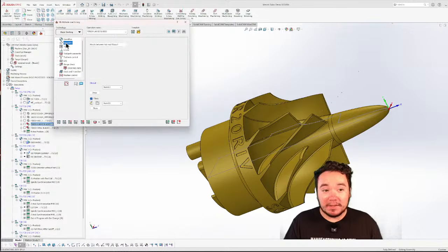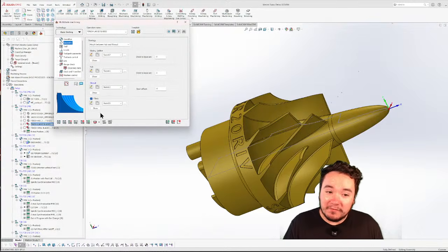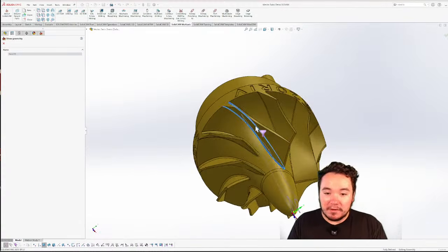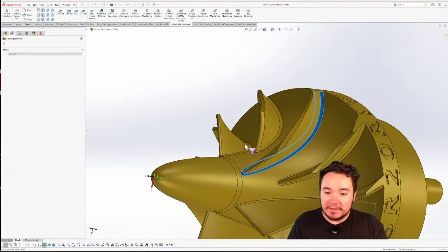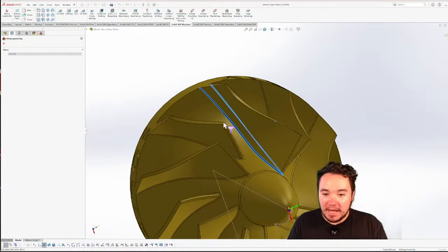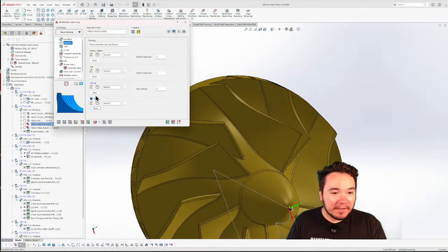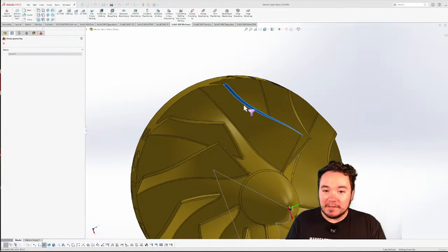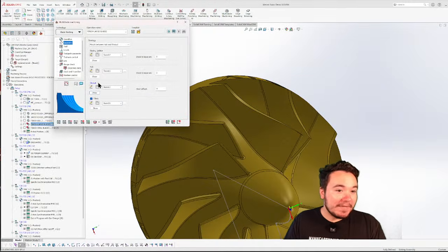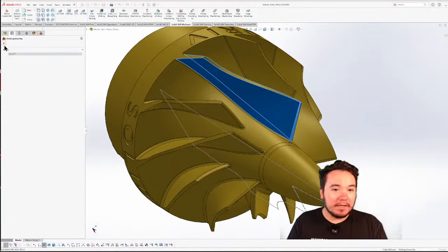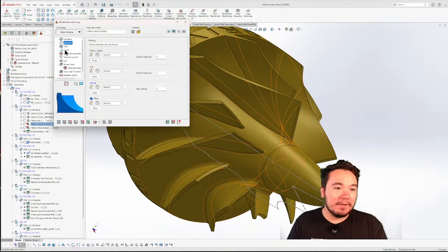This is the blade finishing. This one's a little bit different. I did select the fillet, so the bottom of that specific blade, which I was doing the large blades first here. And you can see just the bottom fillet, the edge between the hub and the blade face itself, is going to be the fillet. The shroud is going to be the top of that blade. That's what that is called in our software. And then the hub, and then for the blade, I only chose the single blade for this one, just so I could get one blade at a time here.